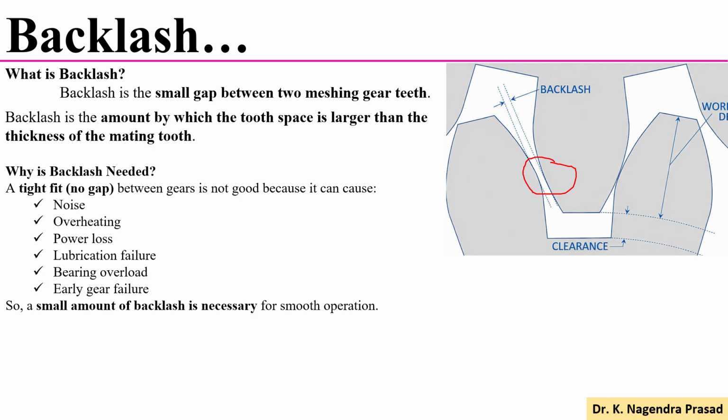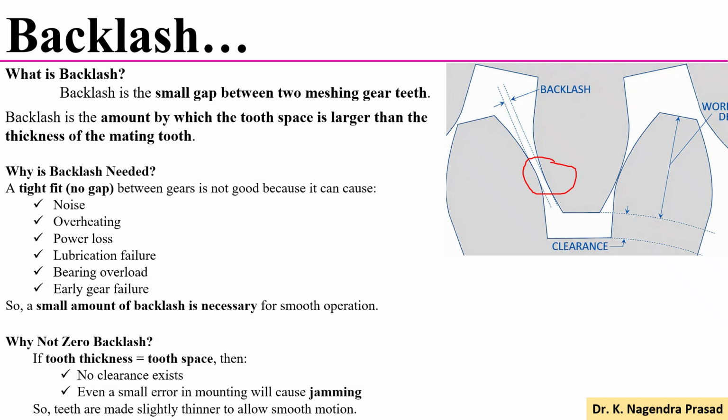Let's see what is the need of this backlash. A tight fit between gears is not good because it can cause noise, overheating, power loss, lubrication failure, bearing overload, and early gear failure. In this regard, a small amount of backlash is necessary for smooth operation.